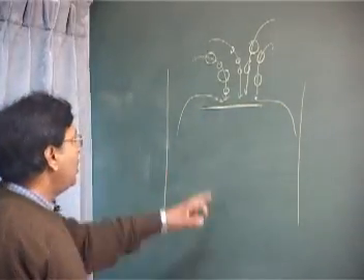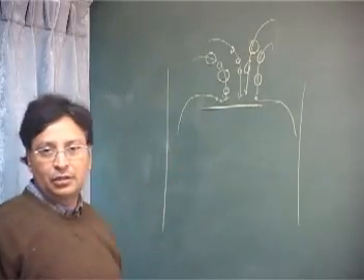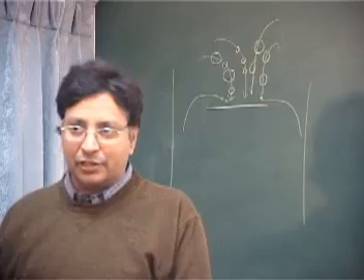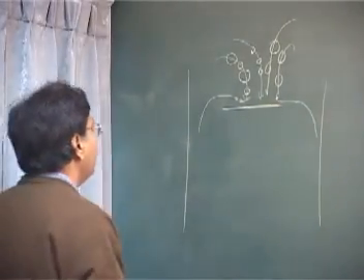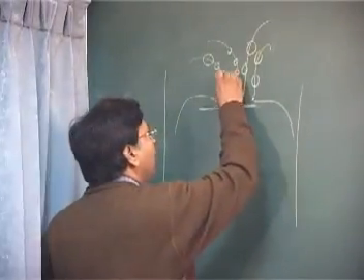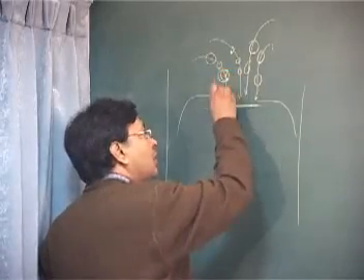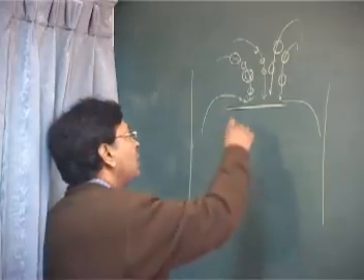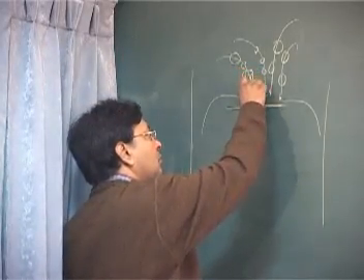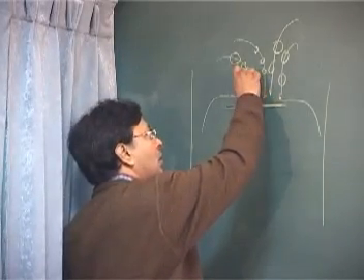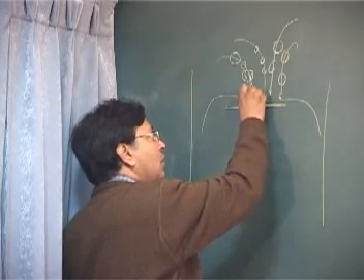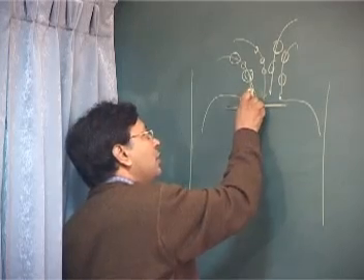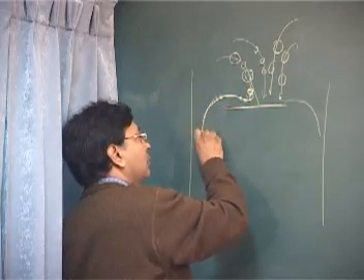Now, even amongst the particles, the larger particles will have more inertia, right? So the larger particles tend to separate out from the stream because they have the inertia, so they will try to travel in the same direction. Whereas this small particle which you see will escape, or will try to go along with the gas stream.